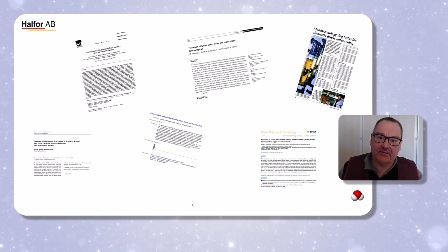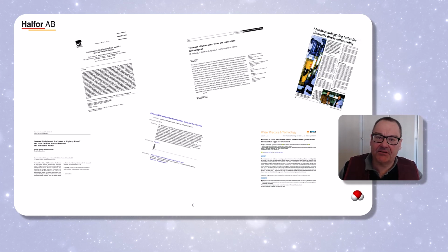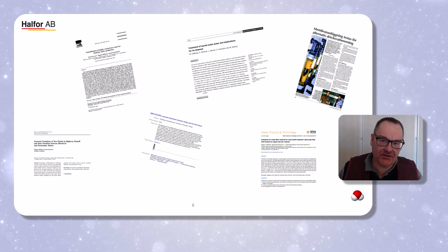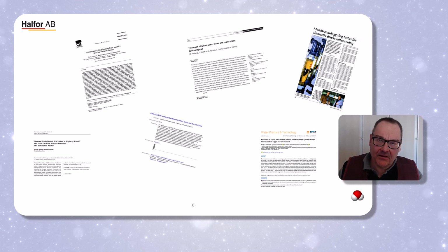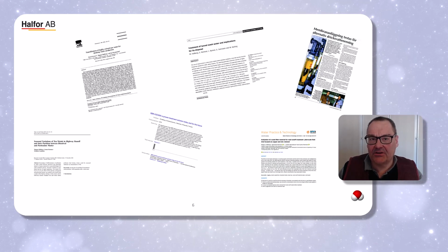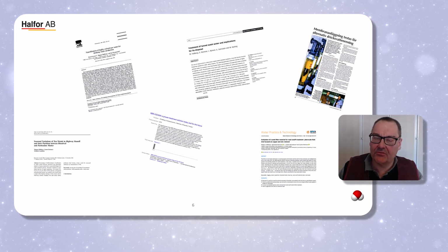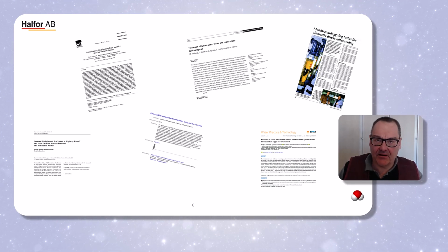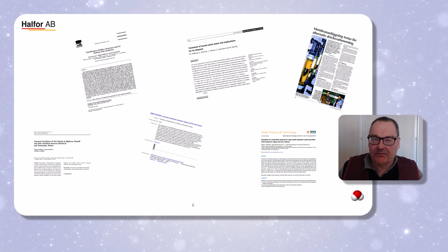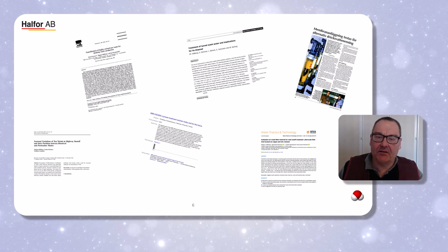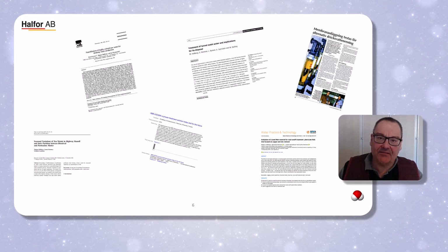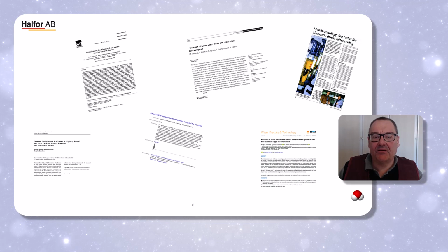If you're looking at complementing an existing treatment process or building a new treatment plant, waterworks, process, or wastewater, in my experience, doing a pilot trial is a very good way of resolving all the issues with the water line, that is, how to remove the PFAS, and also how to take care of the waste that the process you select generates. The question has many times been the cost of a pilot trial, but given PFAS, I would argue that doing a pilot trial will be very, very cost efficient.